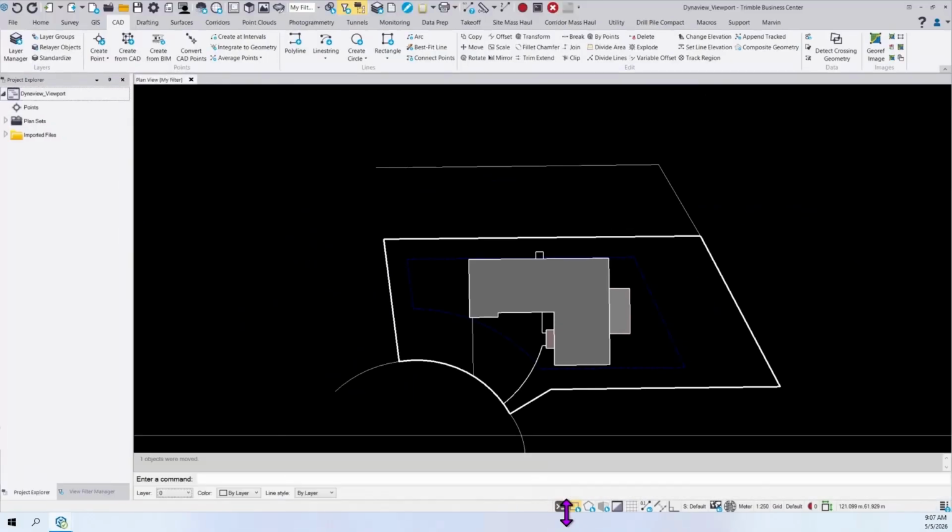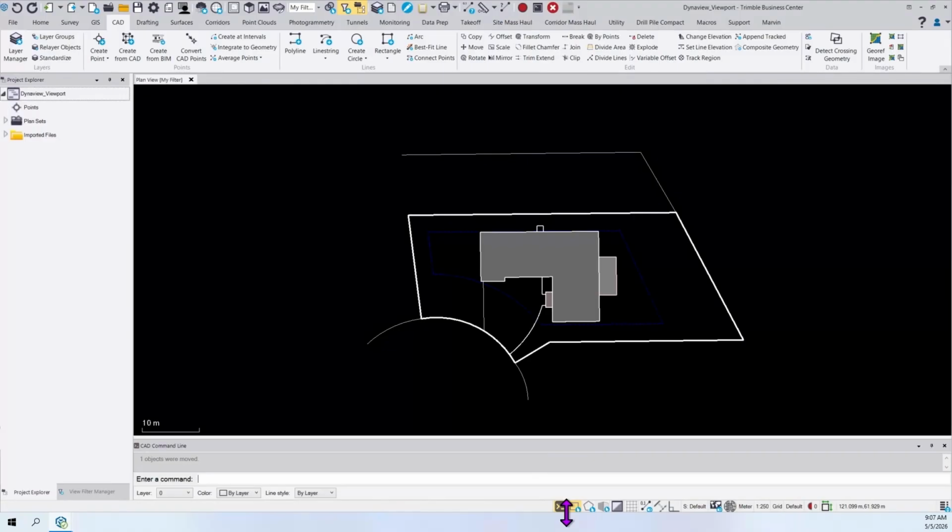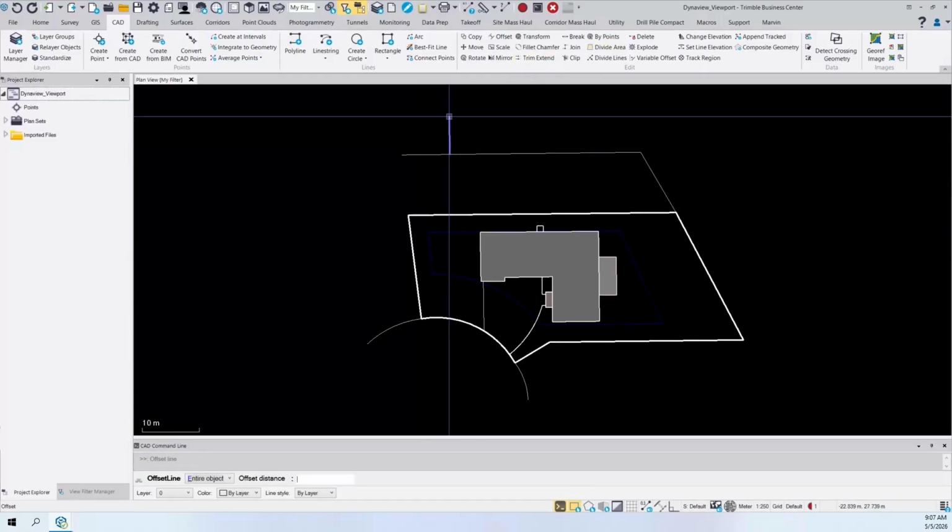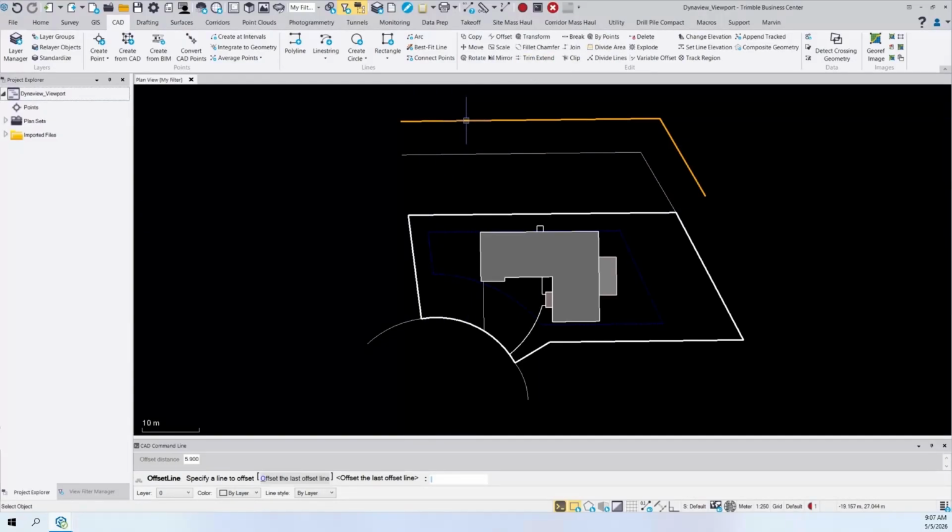If you tap on this, it opens up an interface that allows you to actually either type in the full name of the actual thing you want to do, or hotkey to quickly get towards the function. So let's look at an example together. Let's say, for argument's sake, I want to move or I want to offset this object. Well, I can come in and I can type in offset, and there is the actual function. Tap enter, select anywhere, and then I get an offset, right?